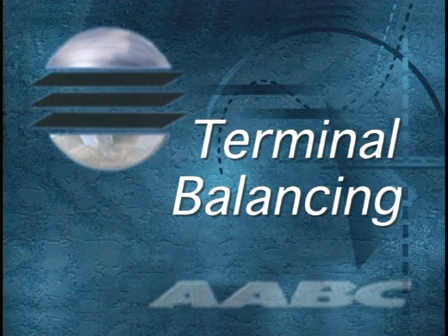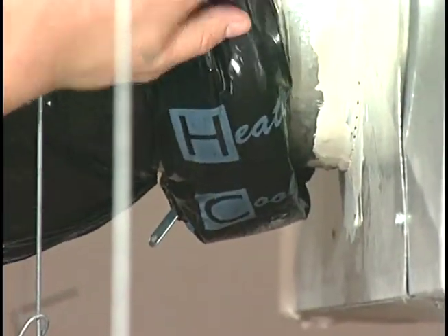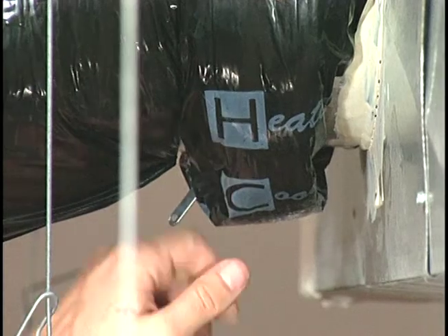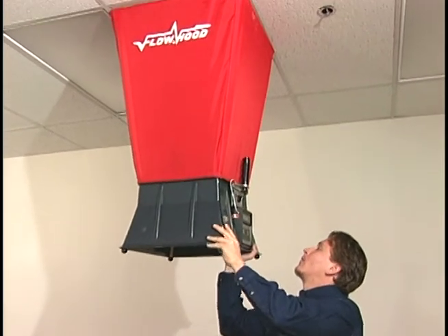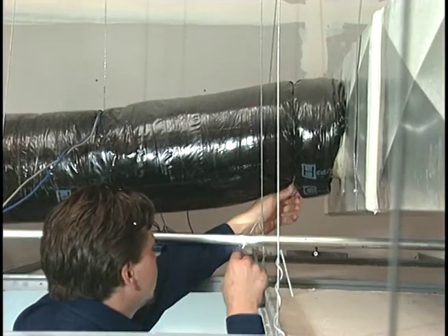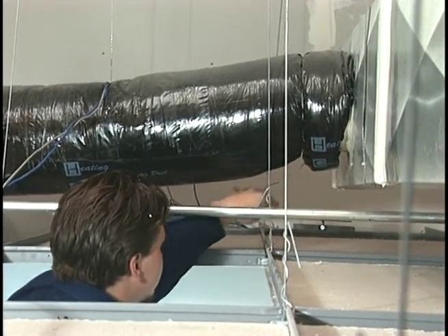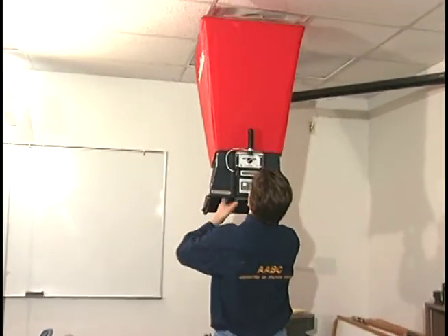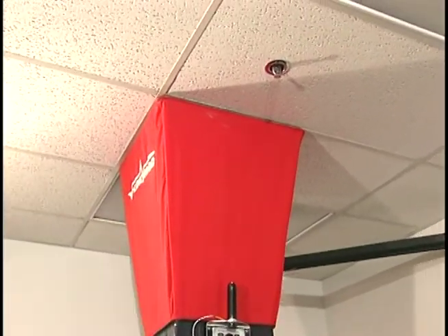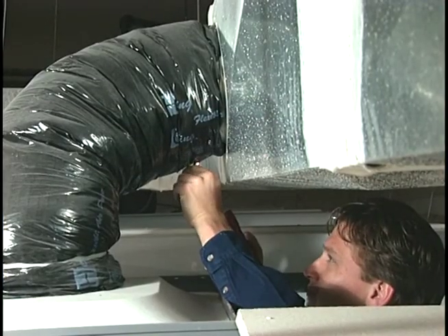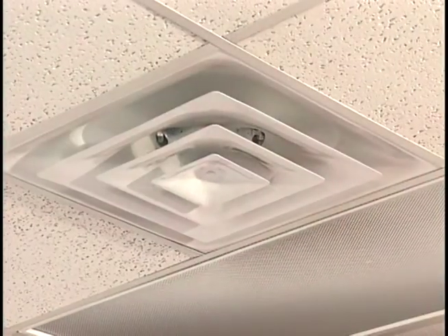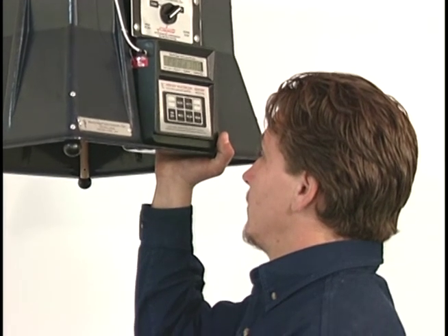Terminal balancing. After all the branches are adjusted to within 10% of desired airflow, the technician proceeds with balancing the outlets. The technician begins by measuring flow at the outlet nearest the supply fan, and then reduces any excessive flow by dampering at the takeoff to bring the airflow within 10% of desired flow. Then the technician moves to the next outlet on the same branch and adjusts that outlet's takeoff damper as needed. The technician continues balancing outward by branches until all the outlets have been adjusted, making 1 or more passes until an acceptable balance is obtained.